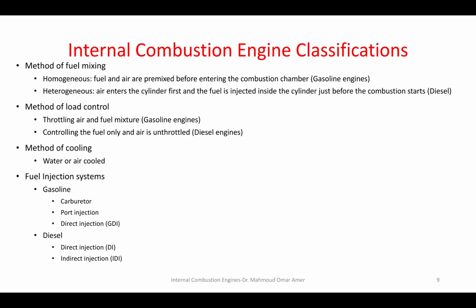The method of cooling for the engine is water or air cooled. For the injection systems in gasoline, we mentioned that we have carburetor injection and port injection, like the L-Jetronic, K-Jetronic, Motronic. Okay? And the GDI, which is the direct injection, which is the MED Motronic.